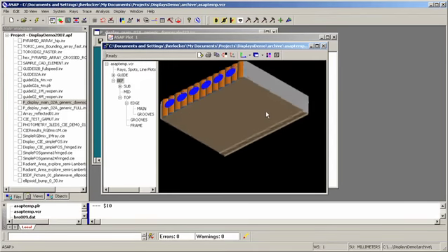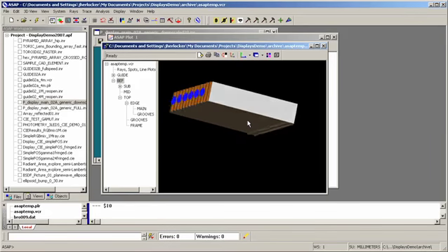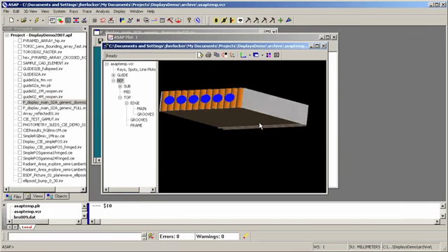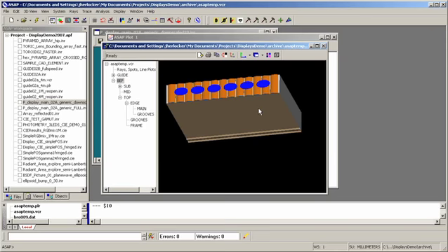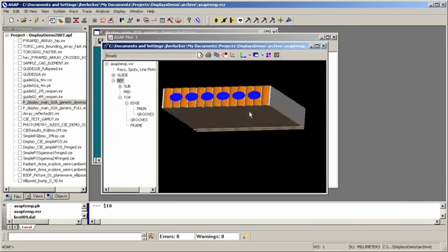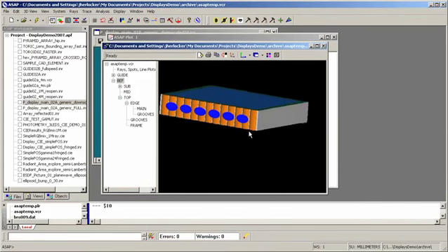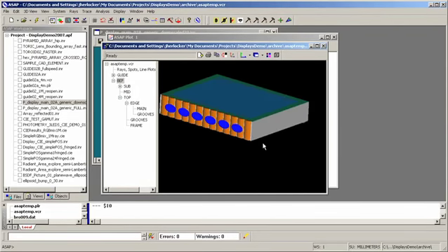Finally, on our tour of this, we have a 30-micron sawtooth on the bottom. The specific angles and things don't really matter for the purpose of our discussion, but we have a sawtooth that is used to selectively couple some of the energy down into the bottom reflector while totally internally reflecting the rest of the energy back up into the guide so it can continue to interact with the top surfaces.